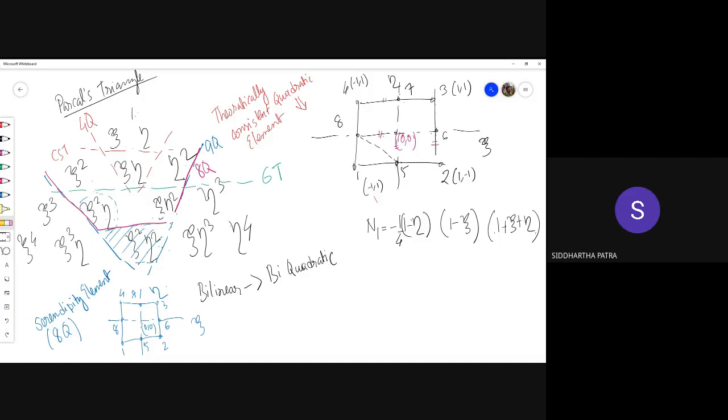Okay sir. And it also cannot be the line containing, you see, the shape function must be 0 at 5 as well as at 2, but it is non-zero at 1, hence you cannot take this line. Similarly, you cannot take this line. Yes sir, but by taking this line 4 7 3, you can set it 0 on each of these nodes. Similarly for 3 6 2. Then you only have to take care of 2 nodes, and you can of course construct a line through 2 points. So that is the simplest way to arrive at a shape function.